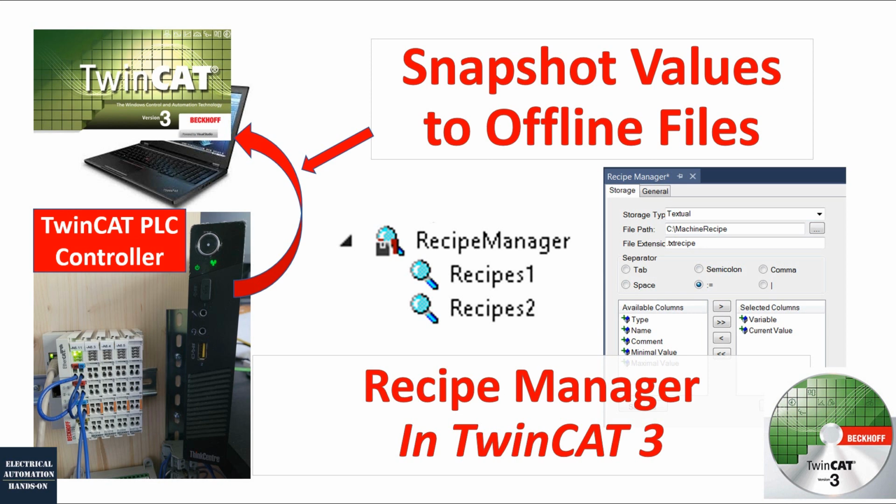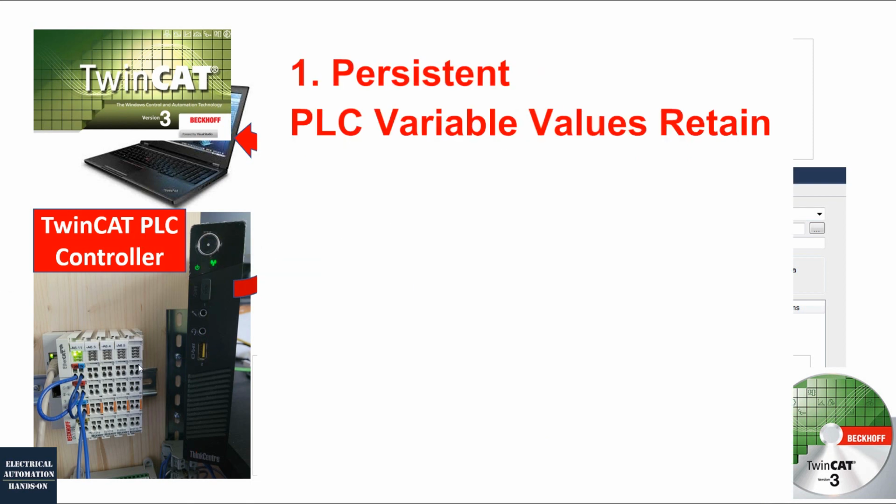Before we start this topic, I do want to review another topic. The first one is variable persistent. Variable persistent allows you to archive all the values in the controller. For example, in this picture, this computer is running as the TwinCAT PLC, running as the controller. Basically all Beckhoff systems run on a PC, so if the PC power shuts down or the Windows system shuts down, can the important values be stored in the PC, and after the system restarts, can all the set points recover?